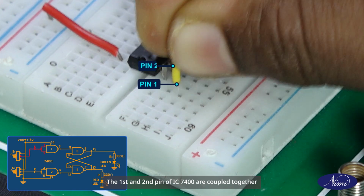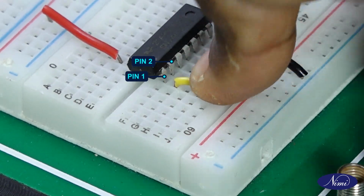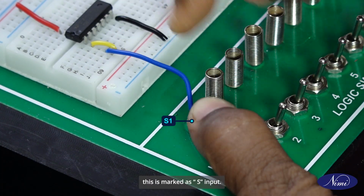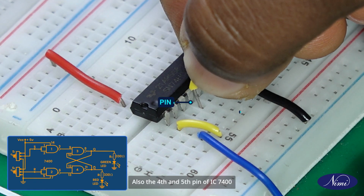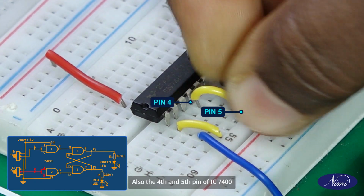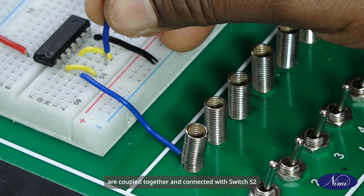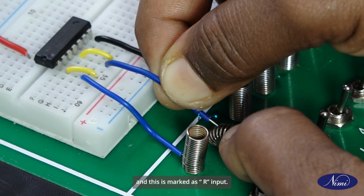The first and second pin of IC 7400 are coupled together and connected with switch S1. This is marked as S input. Also, the fourth and fifth pin of IC 7400 are coupled together and connected with switch S2, and this is marked as R input.